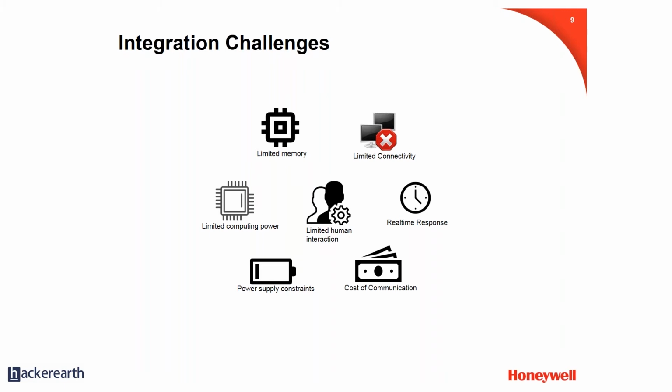And one of the last ones, which I referred to in the previous slides, was very limited human interaction. This becomes important in the design of your edge devices: they have to be self-sustainable. If they get into a deadlock, there should be a way to unlock or reset it. Your watchdog timers, I hope people are familiar with these concepts, but you can look them up if you're not.